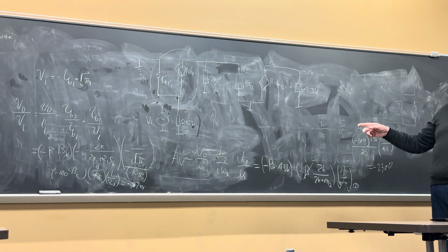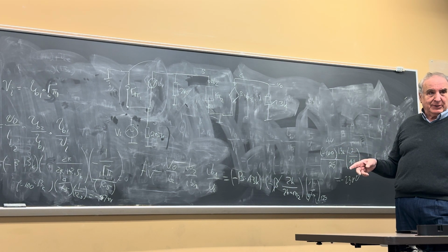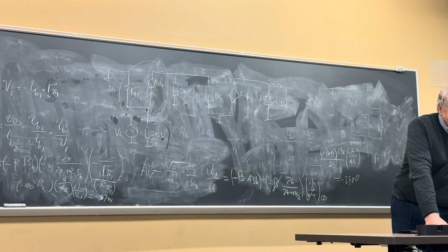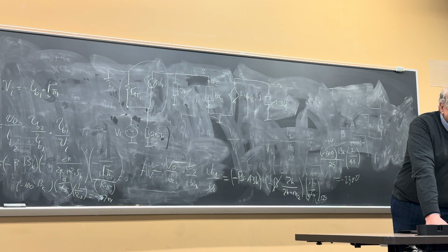You cannot, in other words, if you build this in the lab, you have to put a very small signal in the input. Otherwise, it's going to clip like hell, because 4,000 times 1 millivolt. You put 1 millivolt sine omega t, what are you going to get on the output according to this problem? 4.7 volt. Yeah, 8.7 volt peak to peak. It's gonna clip like hell. Why? We just erased our graph. It can only swing 2.7 up and 2.7 down.